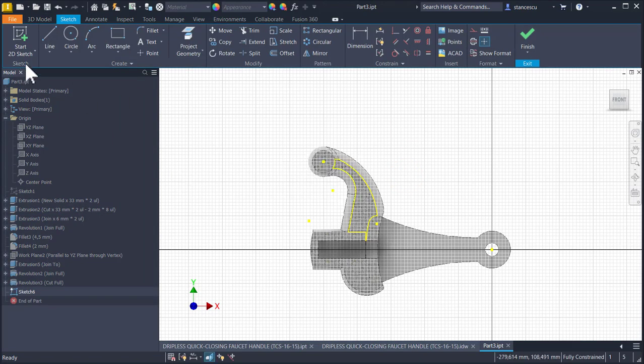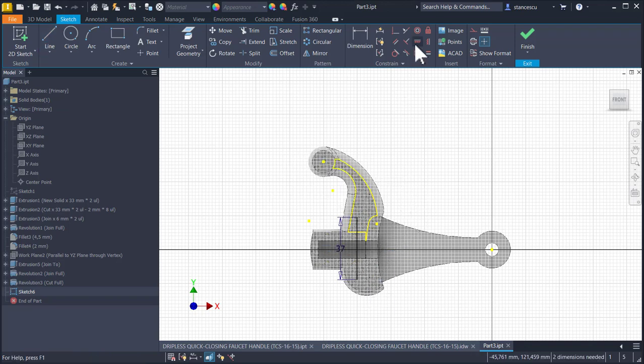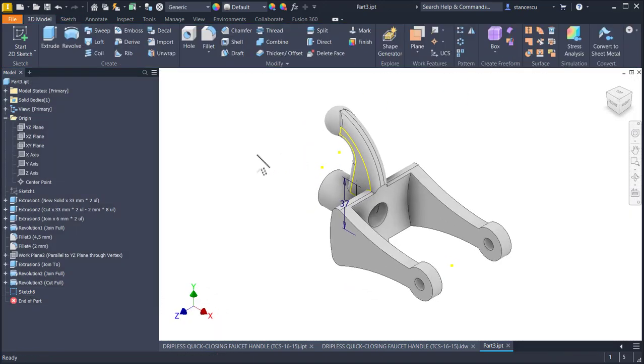F7, I draw a line, a vertical line of 37. I place its midpoint on the same horizontal with the center point. Then I place 2 points at the ends of the line to show Inventor where I want to place holes.